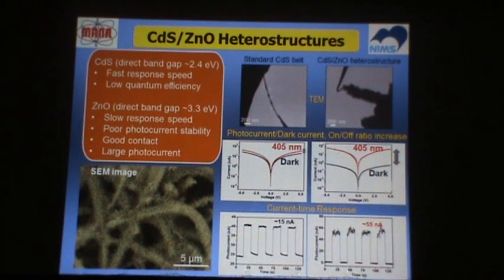Same experiments are possible for cadmium sulfide nanobelts. You know, cadmium sulfide is a very important material for flexible electronics, and we designed this experiment to analyze how the performance degrades when we bend the structure. It really degrades. You can see photocurrent drops from 0.73 to 0.54 after the bending inside TEM. Molybdenum disulfide nanosheets were also studied recently. We get a very clear photo response, and at the same time we analyze atomic resolution and crystal structures, different heterostructures.